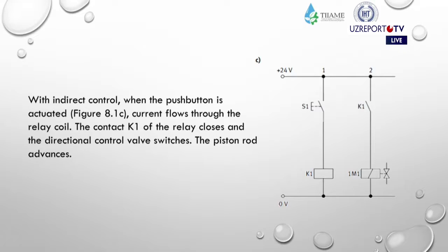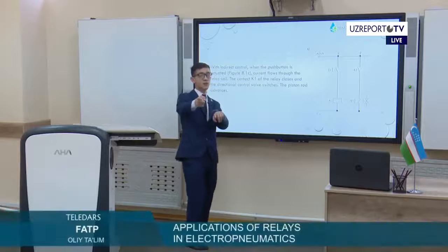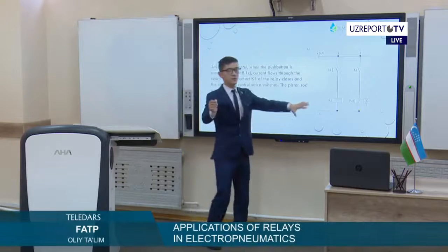It didn't start because here we have an indicator of voltage. If it's not enough, processes don't start. You need to supply enough voltage for K1. We can say that it's a special protection system at the same time. This is a scheme for using the voltage and protection from a low voltage.